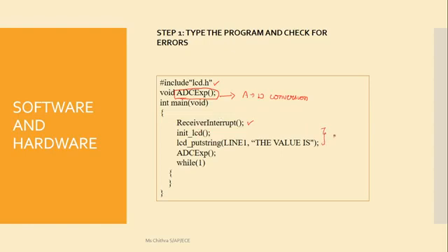The next two lines are for displaying on the LCD. To begin with the LCD, we need to initialize the LCD first, and in the next line, I need to print whatever we have to print on the LCD. The LCD we are using is the 16x2 LCD. 16x2 is nothing but two lines where in each line I can display 16 characters in total.